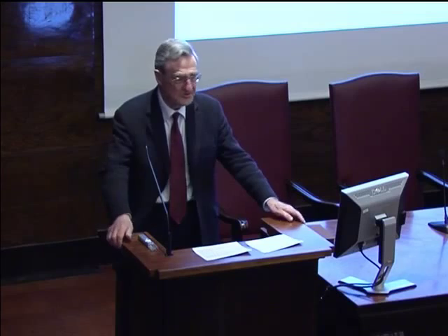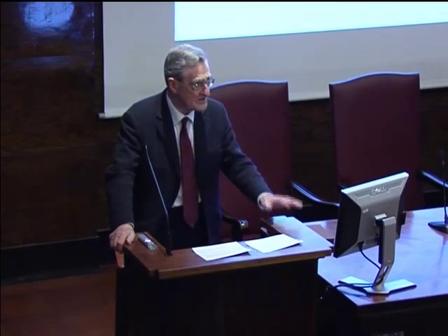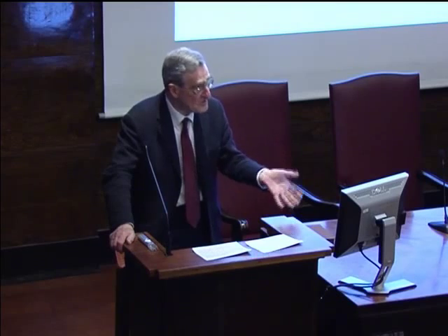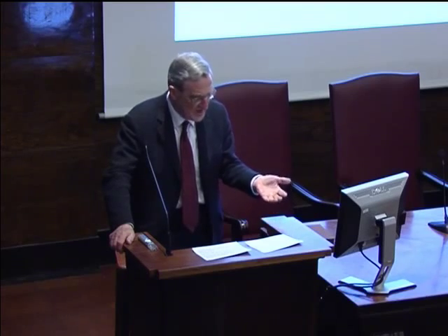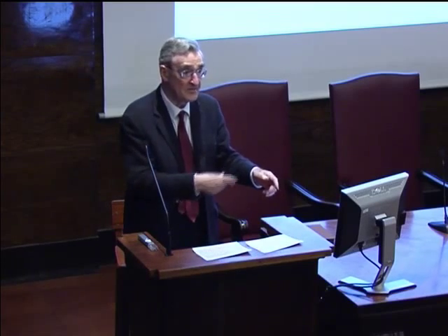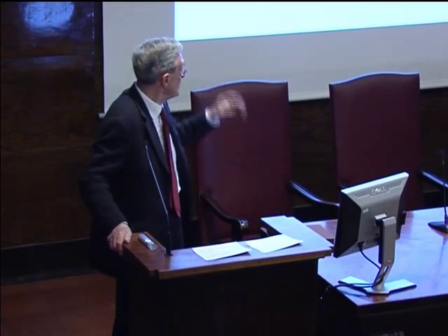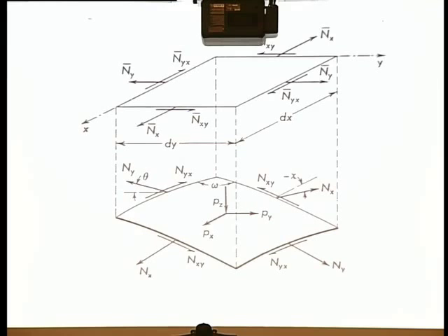And finally, one must write the so-called compatibility conditions. And normally, these merely state that the structure is sitting on supports, and we know where those supports are. There are boundary conditions placed upon the solution, which must enter into the analysis in order to obtain the final solution to any particular problem. These boundary conditions are what we call displacement boundary conditions. That is, they define movements or non-movements, rigidity, at the boundary. We have nothing of that in our membrane analysis of shells.